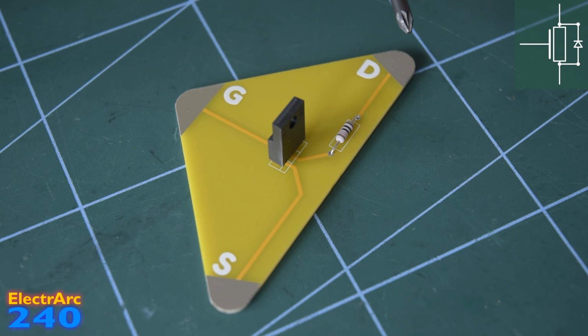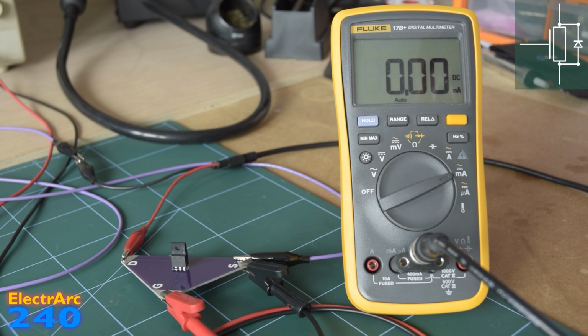something that modern fancy gate driver chips are able to do, with a feature known as DSAT, which essentially monitors the drain source voltage when the MOSFET's turned on, and if it sees it suddenly going up when it shouldn't be, these gate drivers are actually fast enough that they can turn the MOSFET off and save it. It's very impressive. So let's take a quick look at saturation in action.